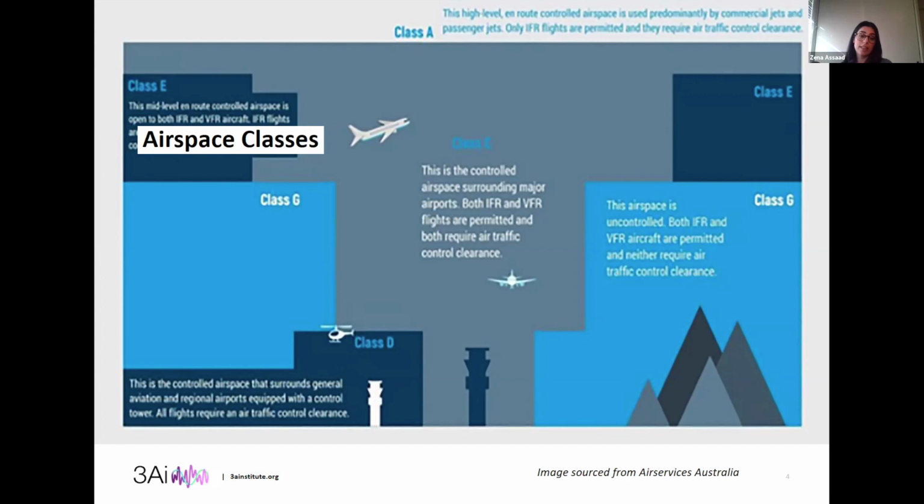Interestingly, the different classes don't have a minimum altitude boundary. The airspace classes are essentially applied from the ground up, which means that technically aircraft flying in low altitude airspace within these classes would have to adhere to the rules of the airspace that they're flying within. But currently ICAO and the Australian regulator CASA don't reference airspace classes with respect to RPAS. There are plenty of standards around maximum flying altitude, limitations around where RPAS can be flown, etc.